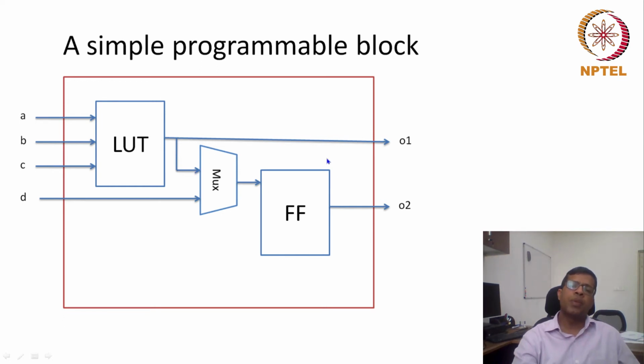So this way, this particular programmable logic can either implement any 3 input combinational logic, or it can implement one D flip flop, or it can implement both: one D flip flop as well as one 3 input non-latched output. So this way one simple programmable block could be implemented as a different type of logic.